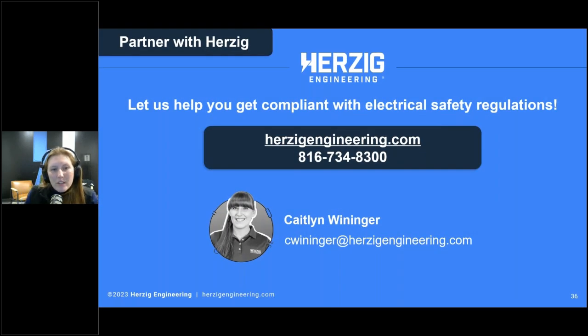When you're making changes on the fly to your one-line drawing, at what point is a new engineer stamp required? Kelsey, fantastic question. So for creating the one-line diagram, not necessarily. However, if you use that to perform a calculation, so if you rerun those calculations, then an engineer needs to review it and stamp on that drawing or the report specifically. Because on one hand, if you're just documenting what's physically there, that's one thing. If you're using that information for a study, that's an engineering stamp required.